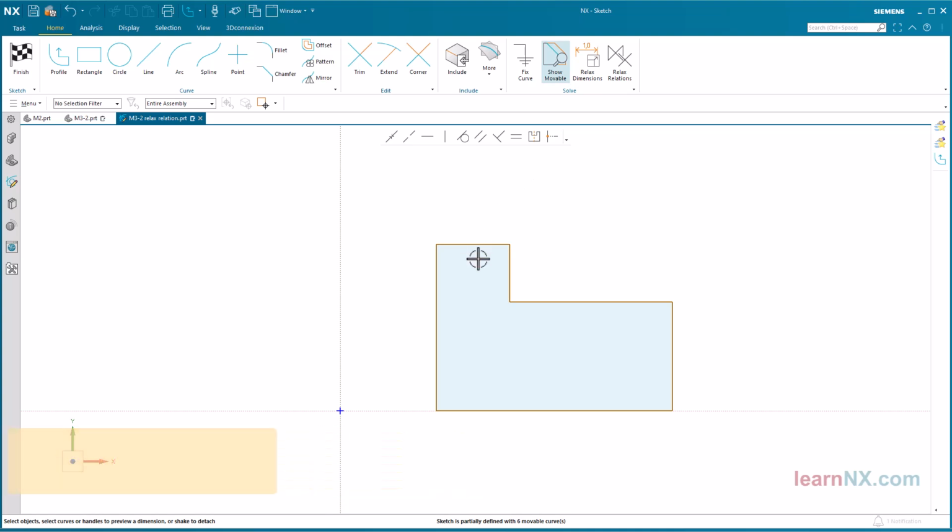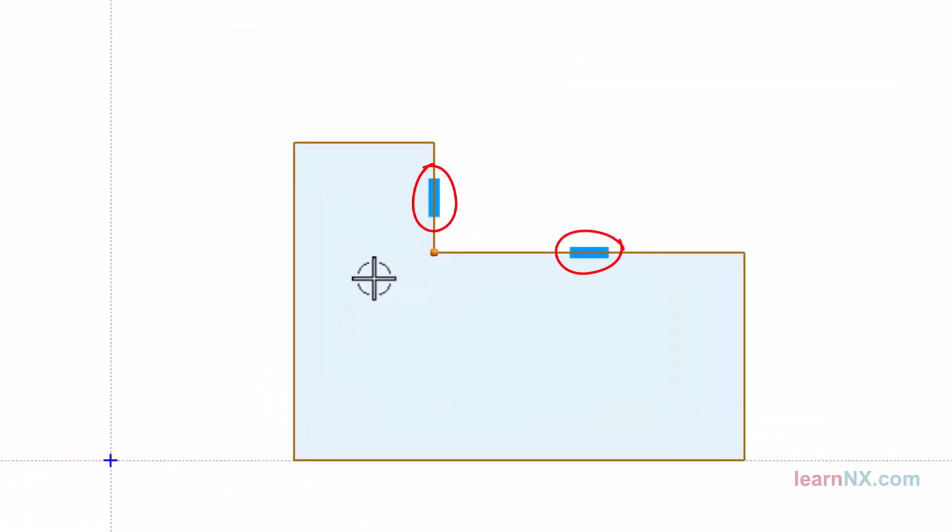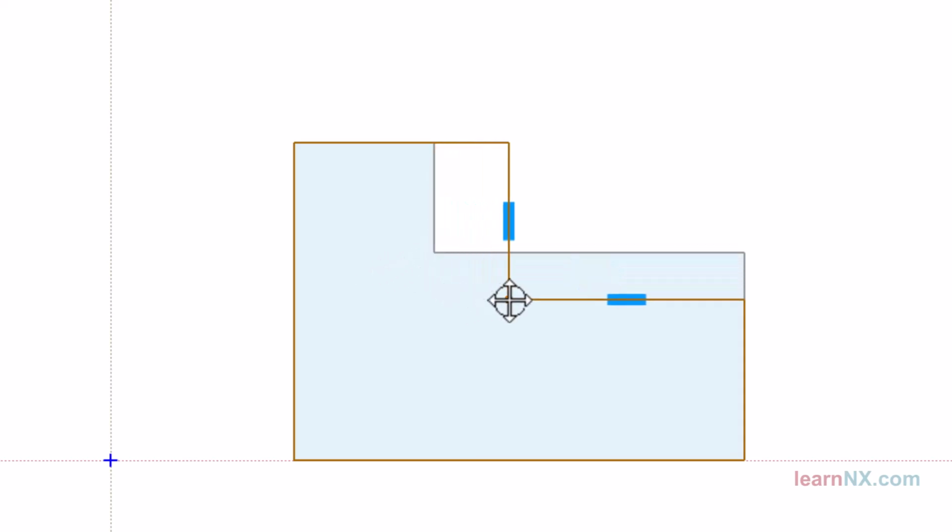When an object is selected in the sketch, NX analyses whether the object is exactly vertical, horizontal or parallel, and displays these constraints as symbols. If an object is now moved, connected objects are also moved, according to the constraints displayed. Couldn't all symbols of all objects be displayed permanently?